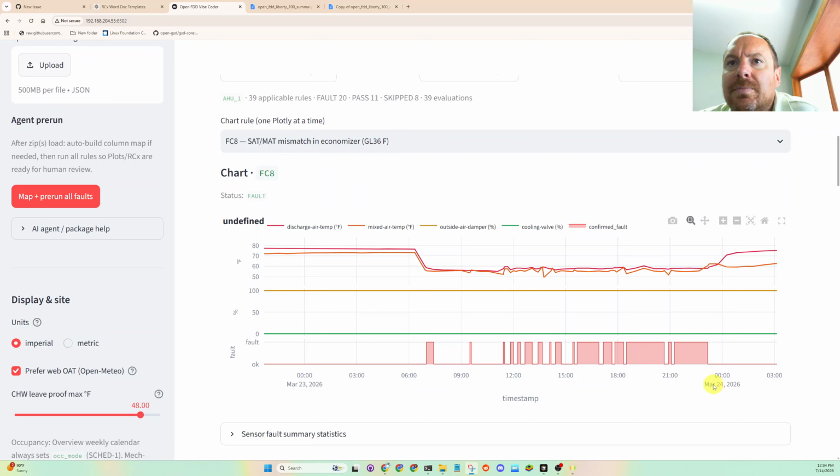Free cooling. This is a great free cooling day. We measure the outside, discharge air temperature and the mixed air temperature. If the air handling unit's in 100% outside air mode, the outside air, mixing air, and leaving air temperature should all be pretty close. And there's just a little bit of a bump on the leaving air temperature. You account for fan heat, which is usually a degree or 2 bump from the fan motor.